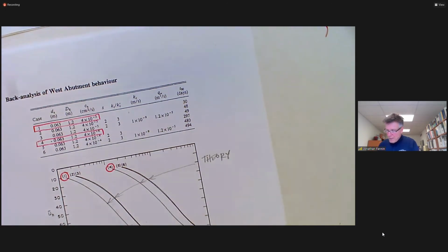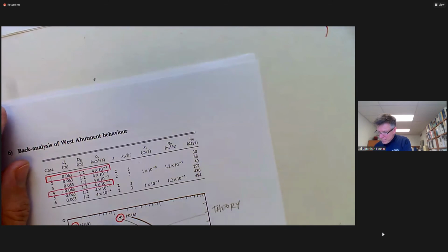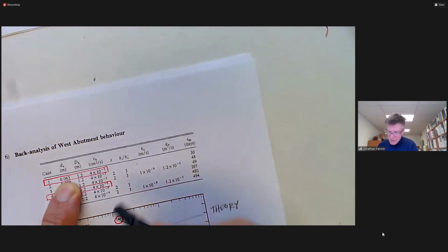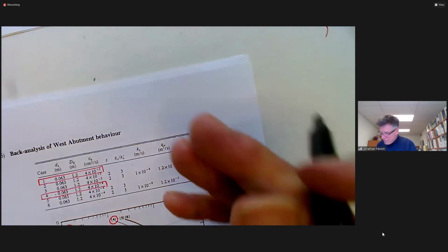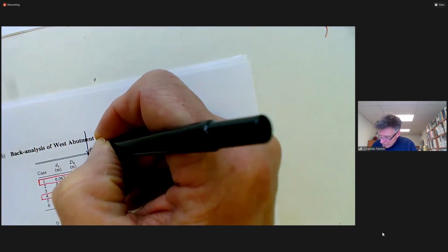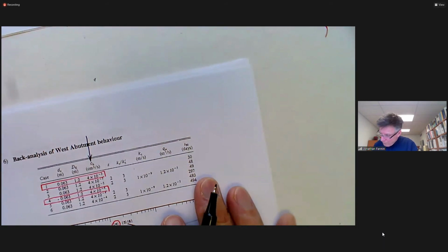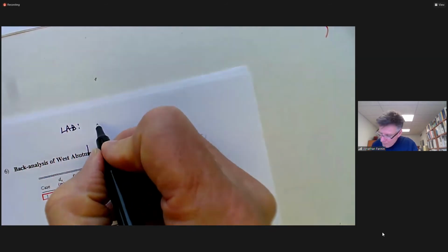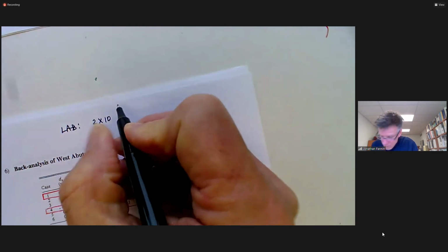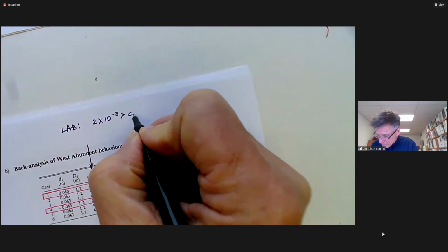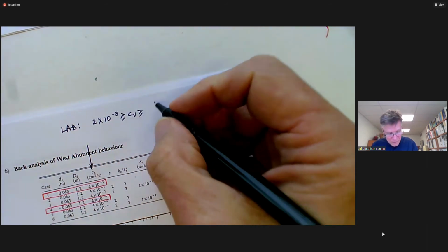Now, where is the value of C sub h coming from? dE is our spacing in the field, equivalent diameter is the assumed circle, and the coefficient of consolidation, C sub h. We know from lab testing that C sub v is in this range.